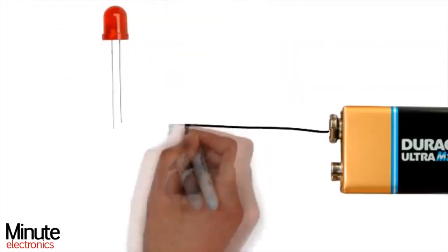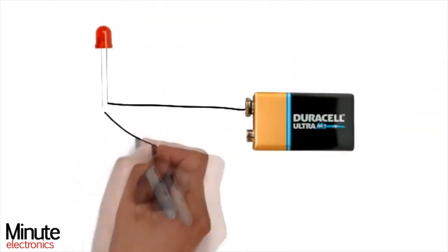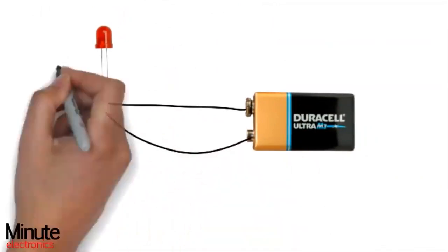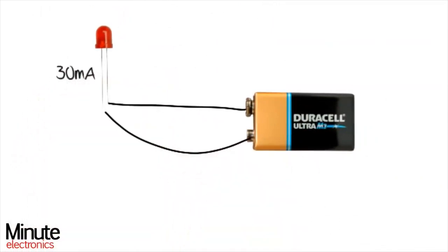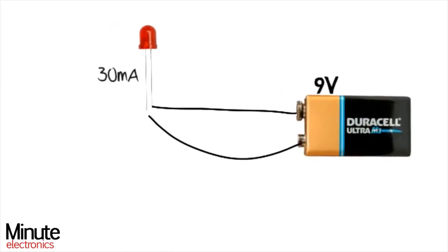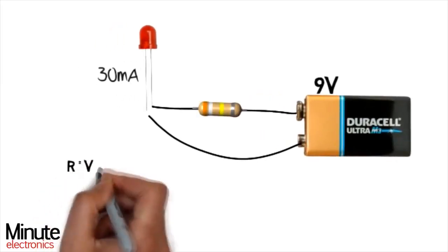Suppose we need to light a red LED having maximum current carrying capacity 30 mA with a 9 volt battery. If we directly connect the battery to the LED, then the LED might burst out instantly. LED practically doesn't create resistance, so the current will get much higher than 30 mA. To prevent this, we need to connect a resistor in between the battery and the LED.